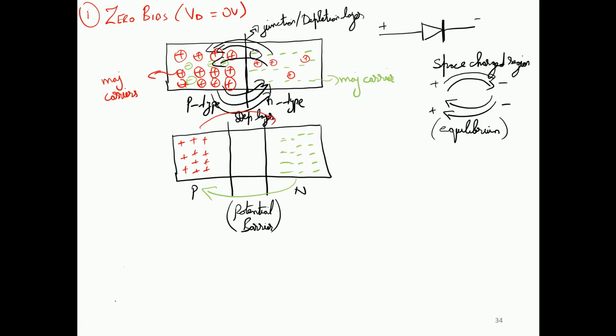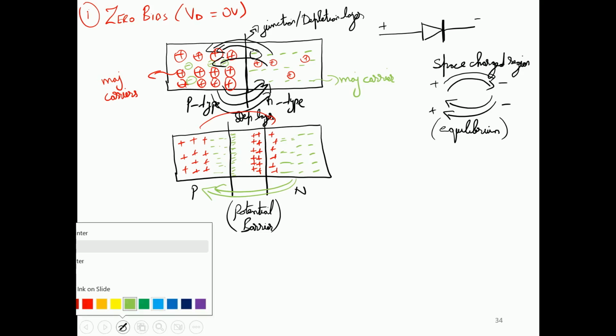We can say that the positive charges, when they appeared over the n-type material, started accumulating over here. So their strength became more due to recombination. Similarly, electrons, when they started moving to this side, started to accumulate over here, and thus their strength increased from this side. So we can say that a potential barrier or electric field got created in this region.